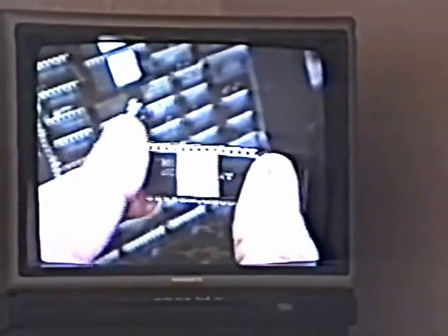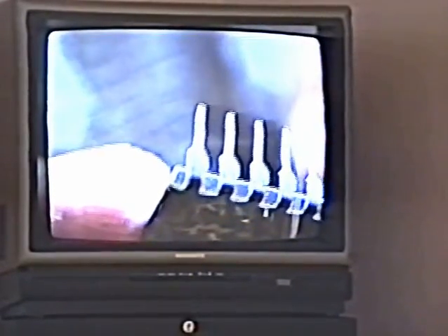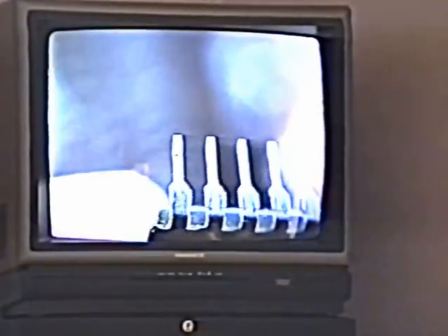The game was still working perfectly, just the images were messed up. When you get the chip out, look at the pins. Are they clean and shiny as these ones are? No problem here. But if you see nicotine and dirt and stuff like that on them, like this pin right here on the corner, you can see a little bit of dirt on them. Okay? Take a pencil eraser, carefully clean them off.